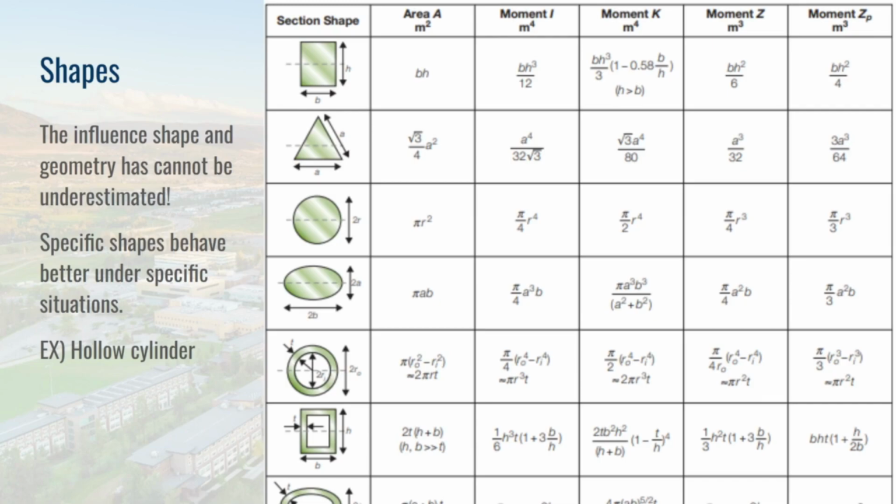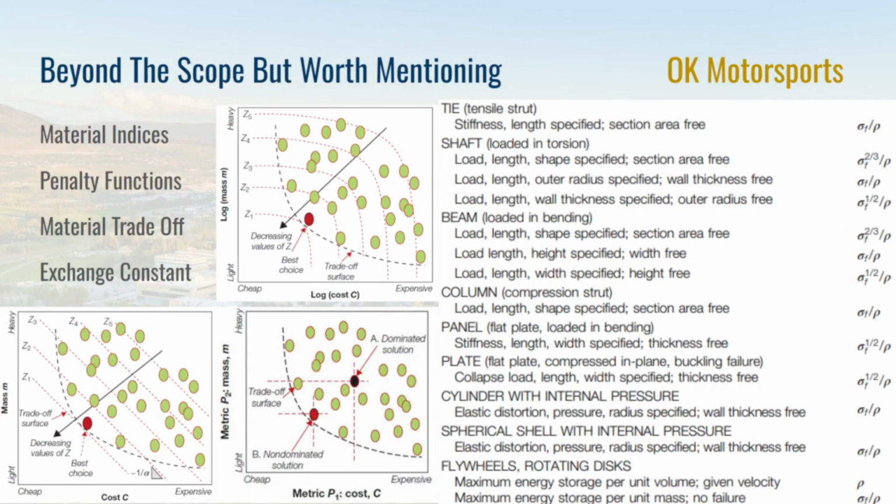And in fact, the SES, which is how we submit our tubing requirements to FSAE, lets you choose between round or square tubing for that portion of the chassis. If you do choose square tubing, it runs a bunch of math using these equations, and decides the minimum thickness required. Square tubing could be thinner in that case because of what it's used for in front of the chassis. There's some other stuff I'm not going to mention tonight because it's just kind of beyond everybody.